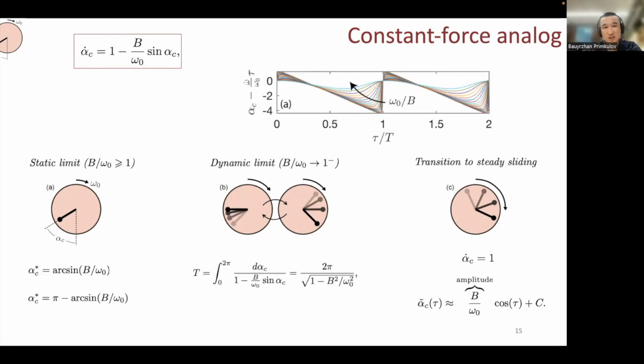And then, yeah, you can simulate this nicely, and you would see the same things. On the y-axis, you see the position of the pendulum. On the x-axis, that's the time. The sharpest graph, the graph with the steepest slopes, that's on the left-hand side, so that's closer to the static mode. And then as you increase the speed, the amplitude of oscillations in this moving frame of reference dies out, which means you're going from stick-slip motion to something that looks more like a steady sliding.